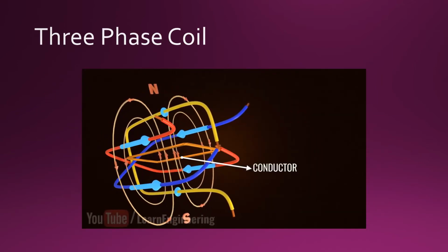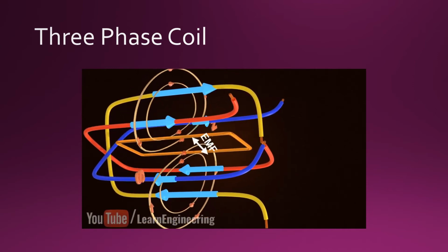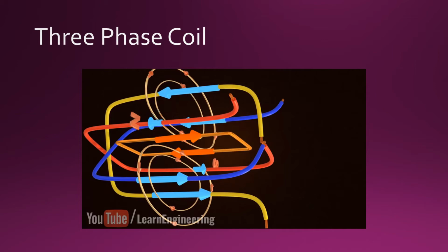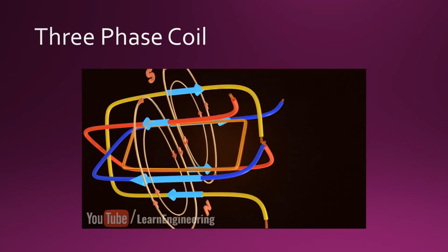So what causes the stator to create a rotating magnetic field? The answer is due to the fact that there are three coils with changing currents. The alternating current supply causes the current through one coil to have a smaller current and therefore a smaller induced magnetic field. The current in this coil then rises and falls to the input of the AC frequency. Since the coils are out of phase and their current rises and falls at different times, the net magnetic field rotates. Faraday's law of induction states that if there are changing magnetic fields, there will be an induced electromotive force on a conducting loop. This force causes the loop to rotate, thanks to the right-hand rule.